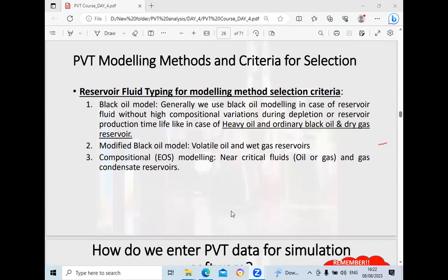All right. So now we are talking of reservoir fluid typing. Typing used in reservoir engineering is just a term to describe maybe changes at different conditions. We have a reservoir pressure that varies between 2,000 and 5,000 psi, and then we say between 2,000 and 3,000 we have a fluid that behaves in a particular similar manner.